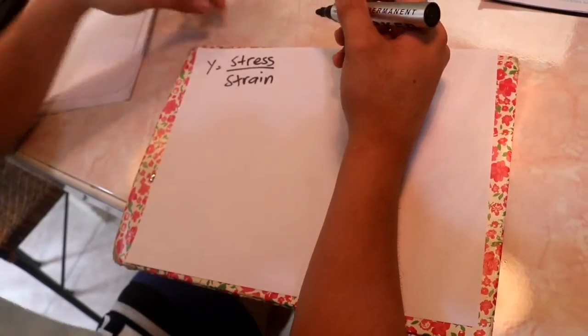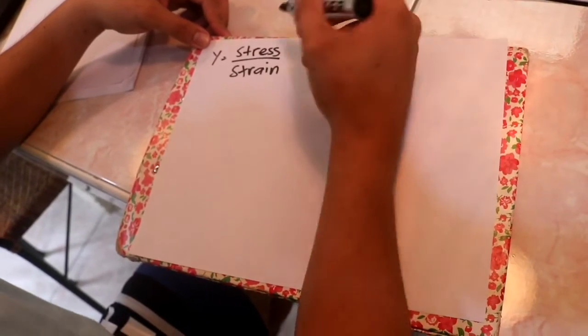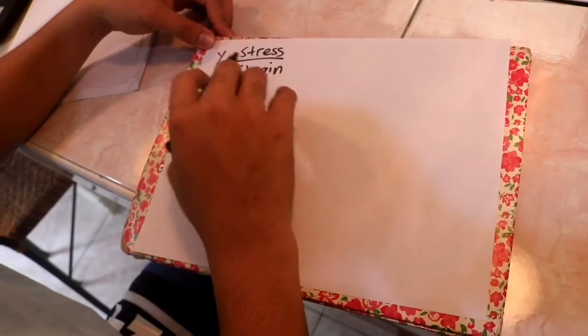So now, I'm teaching you how to solve Young's modulus of elasticity. The formula of Young's modulus of elasticity is Y is equal to stress over strain. The example problem of Young's modulus of elasticity is this. Example number 1. A wire 2 meters long and 2 millimeters in diameter, when stretched by a weight of 8 kg, has its length increased by 0.24 millimeter. Find the stress, strain, and Young's modulus of the material of the wire.